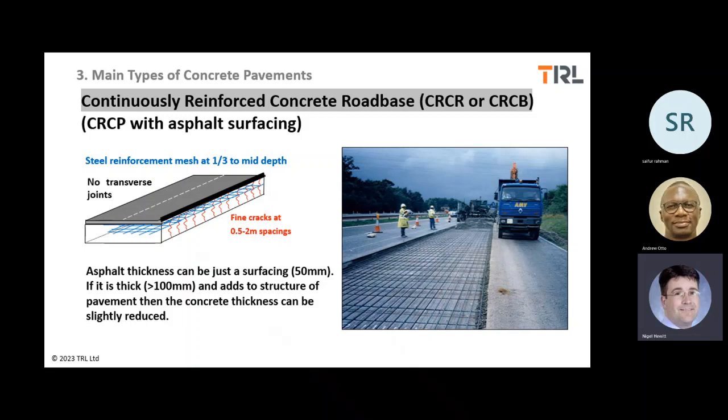And we have used many techniques in our project to reduce the cracks. Cracks are there, but we have been able to produce the cracks with more space, like 5 meters, 6 meters. So there are not so many cracks here. If you can visit our site, you can see it is not so closely spaced. We have provided so many techniques of casting and curing and saw cutting. Many methods have been used in our project.